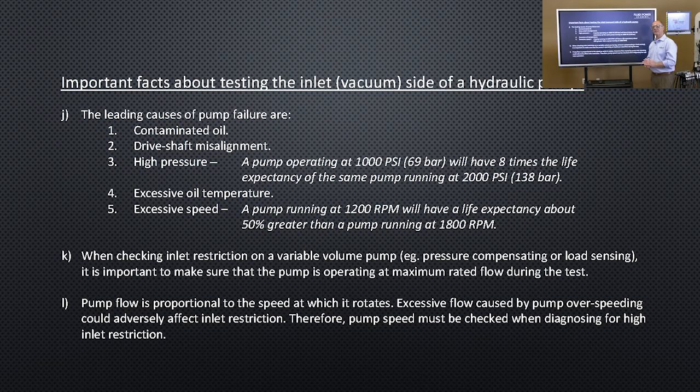Most of the time you can't get the pump fully unloaded anyway, because in designing with pressure compensated load sensing pumps, we never design to utilize 100% of the flow at any given time. So it's very difficult to check inlet restriction or even set the pump's flow if it's got flow adjusting screws unless I can completely unload the pump.